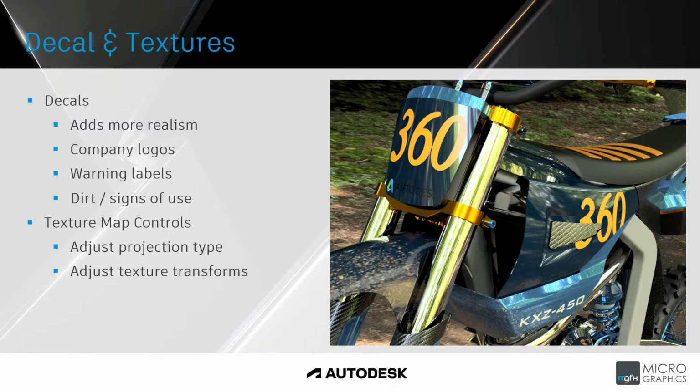Then we get to texture map control. This forms part of the appearance that you assign. So when you assign something like carbon fiber to a component, we can see here on the bike we have the carbon fiber on the side panel and the carbon fiber covers on the shocks. That carbon fiber has a specific texture and direction to it, and we can then adjust the direction of the carbon fiber weave. So we might want to have it currently like it is at a 45, maybe we want that weave vertical on the component. And so you can adjust the direction of the texture.